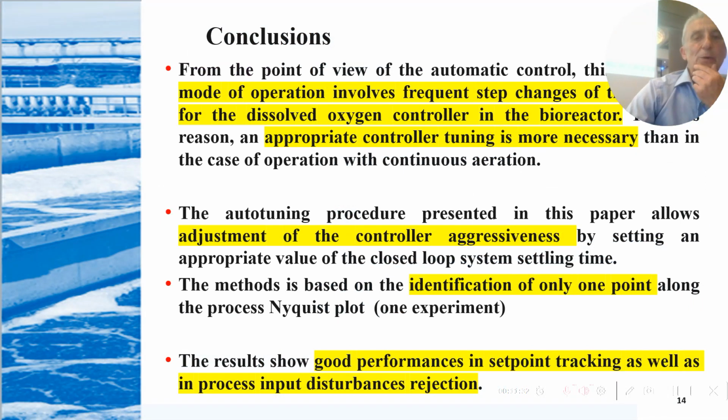In conclusion, we need a well-tuned PID controller. Why? Because this mode of operation, that means intermittent aeration, has frequent steps in the set point. So we need an appropriate, well-tuned controller to obtain good results.